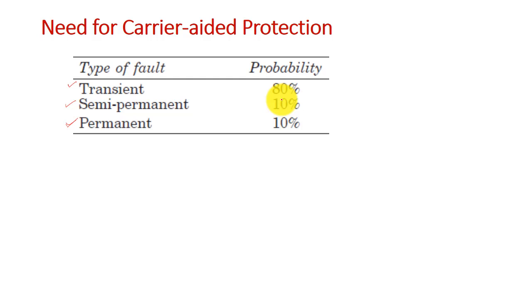In fact, a transient fault is not permanent in nature. It happens temporarily, for a few milliseconds sometimes, right? And it is because of the ionization of air outside the insulator. It is not the insulation breakdown, in fact it happens because of the air breakdown, because of the ionization effect of the air. The fault happens temporarily when there is a certain overvoltage, and when the overvoltage is removed, then it stops. So therefore, how to tackle this?